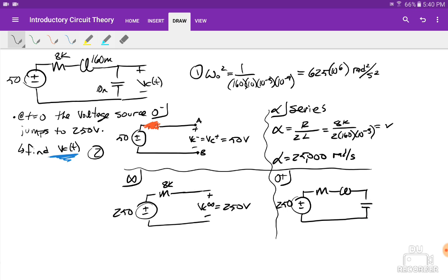Okay, and this I think is one of the trickier parts in solving this bad boy. You still have to use everything you know. All right, so what happens is the current on this inductor is actually equal to 0 because I minus on the inductor is the same thing as I plus, and I here was 0. We solve for that. Therefore, because it's 0, this inductor actually dies away again. Poor baby. And it ends up, instead of becoming a short, it's 0 current now, so I can represent it as an open. Because it is open, I know that there is no current anywhere else in this circuit.